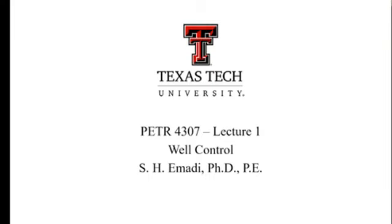the kick indicators, how can we detect the kick, also the causes of kick, the equipment we have on a rig in case we have a kick, and well killing methods, mainly the driller's method and the wait and weight method. And at last, if we have time, I'll talk about the volumetric method, which is not a well killing method, but it is used when we don't have the opportunity to fully circulate.